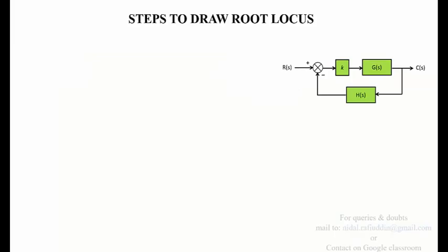With this basic concept in mind, let us now try to draw the root locus with the basic steps by hand. We drew root locus on software like MATLAB, but sometimes it is required to understand root locus, to know how to draw them by hand. So that is why we are going to discuss the steps that are involved.